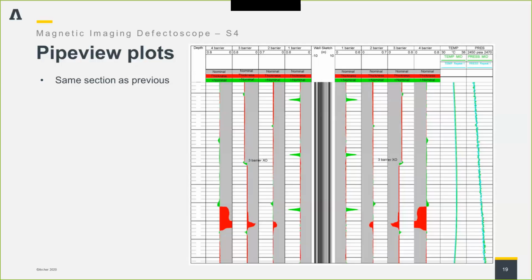I assume that's for surface pipelines and things. But if you have an intelligent pig with a caliper type arrangement on there, or potentially some sort of magnetic flux leakage device or something like that, then it would be working in broadly the same way. But I'm not aware of intelligent pigging that does multiple concentric barriers.